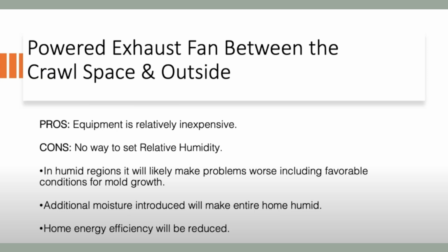It's important to note this only works if it's drier outside than it is inside, as we have been talking about. In the spring, summer, and fall in a lot of regions, the dew point will be too high for this to be effective. Also, if it's cold outside during that time of year, then you're most likely bringing in colder air. This colder air can create colder floors and higher energy usage that no one wants.